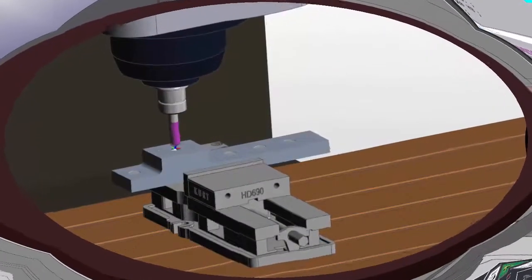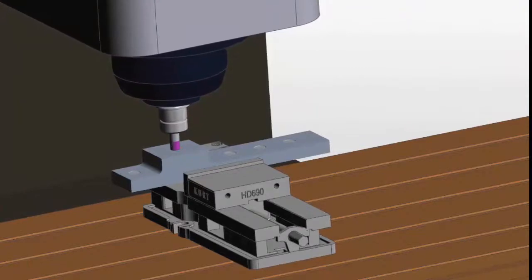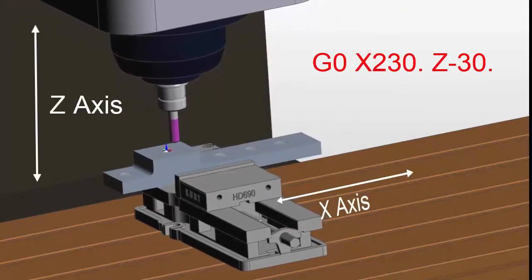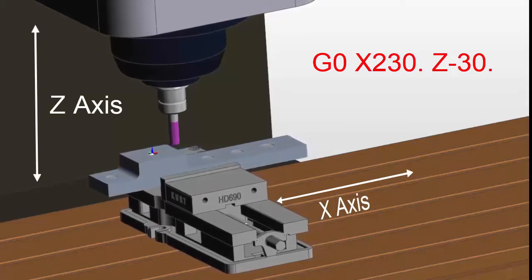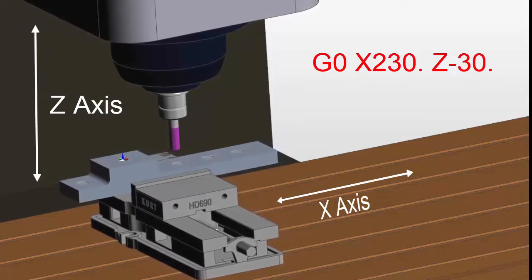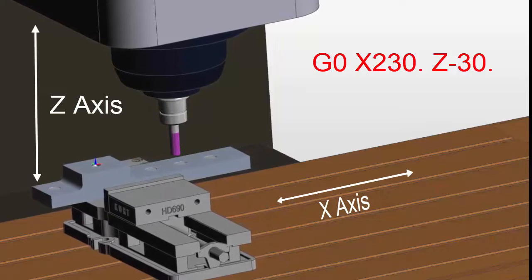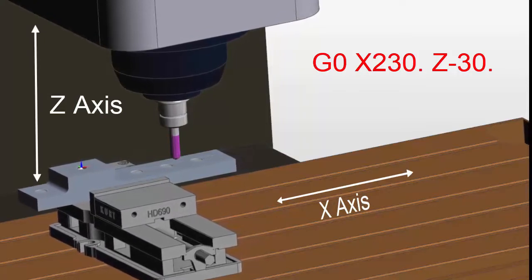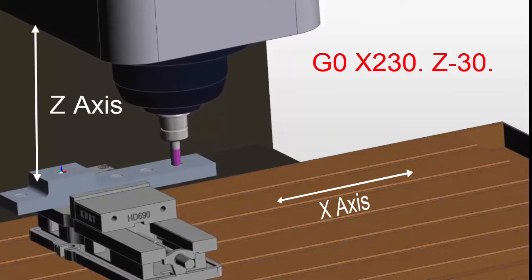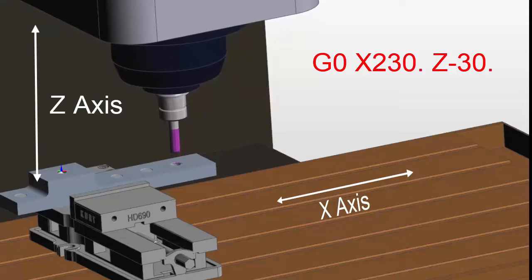So in this component, it comes out of this hole, and I've got a rapid move to X230 and Z minus 30. But this is what you might think would happen. That's almost like you programmed a G1, because that would be a complete straight line. If instead of G0 you had G1, that is what you would actually get. But because we've programmed a rapid move, the axes are both going to be flat out. So it's not actually going to do that.